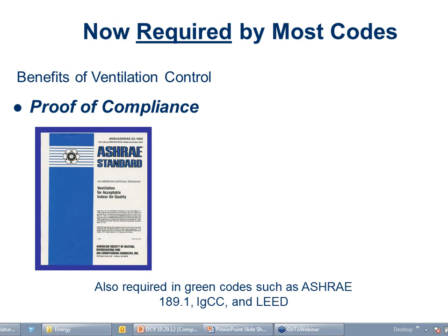It doesn't necessarily mean I need to have a sensor in every single zone. There are some equations. Equation 6.1 from ASHRAE 62 does allow me to put representative sensors in given spaces and then use that formula to try to track it that way. Only one VAV controls manufacturer that I'm aware of uses that as their standard. Everybody else does it by measuring every single VAV box.